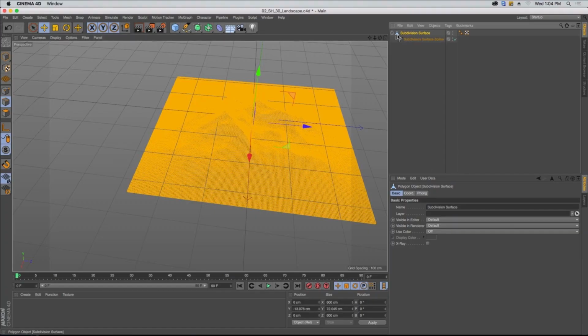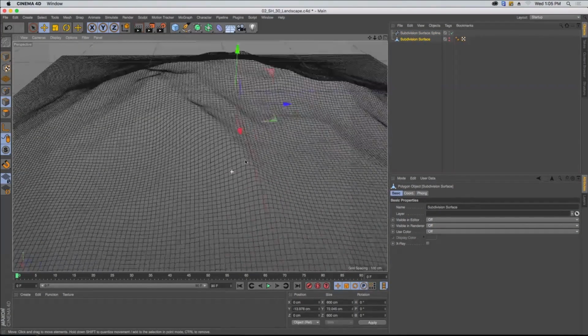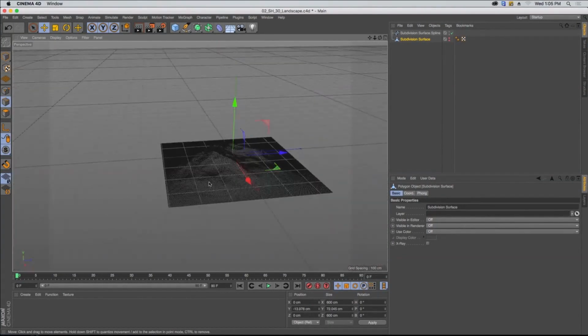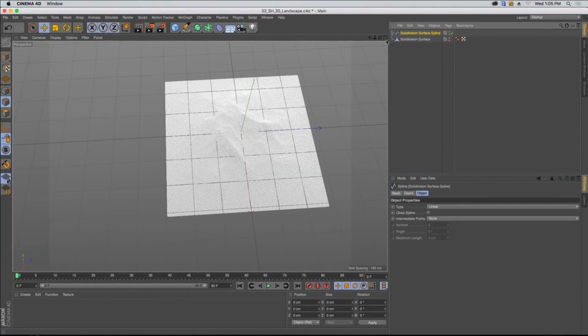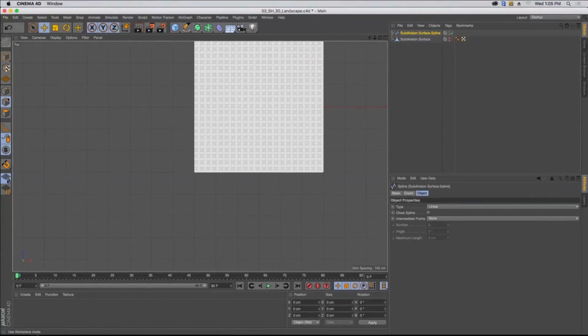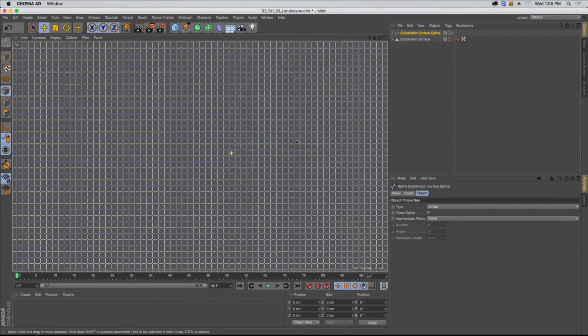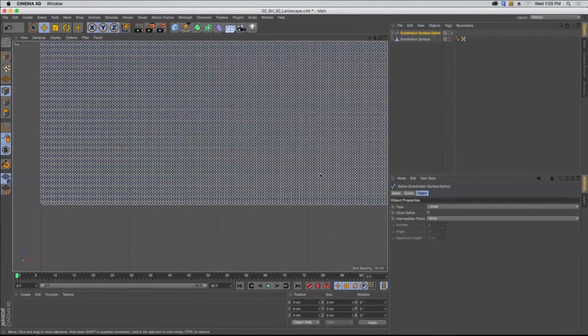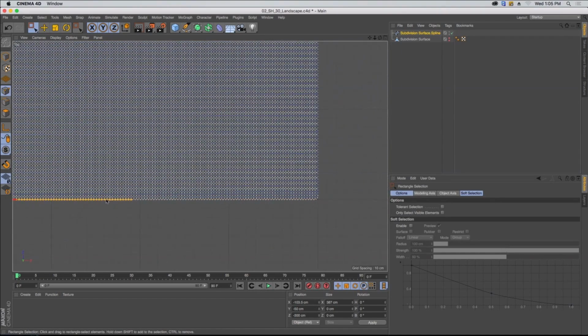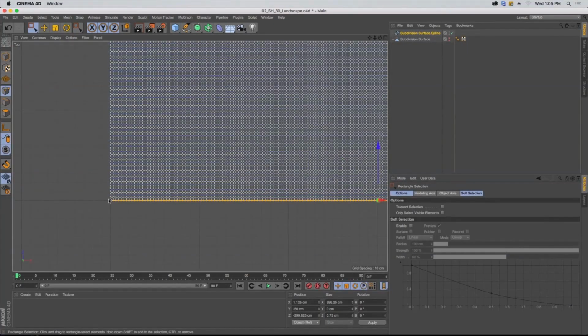That's going to, did it instantly. So what that does, I now have my entire mesh as a spline. Very useful. So now what I can do, if I switch to my top view, full screen this, I can go to point mode, zoom in. I can now select all the points along this edge, like so. I think I got them all, or most of them.